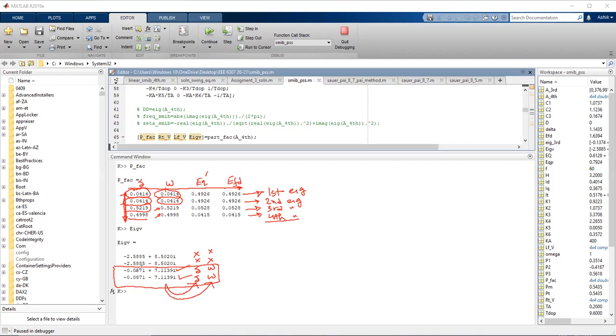Okay, these are the dominant eigenvalues because they are nearer to the y-axis. So that means if I want to design control, I have to look for any error in the delta variable or omega variable, and then I have to feed that error to the controller. That should take care of any deviation of the delta value and omega value. Okay. About the third and fourth, you see the first eigenvalue, you see EQ dash. Okay, there is a very large contribution. Similarly, the second eigenvalue in EQ dash.